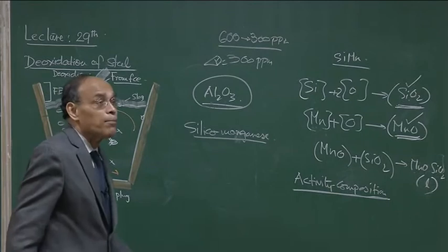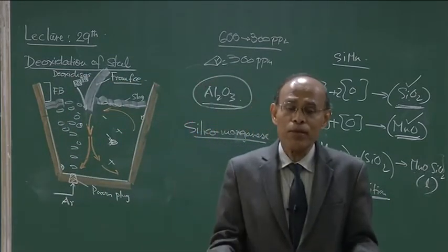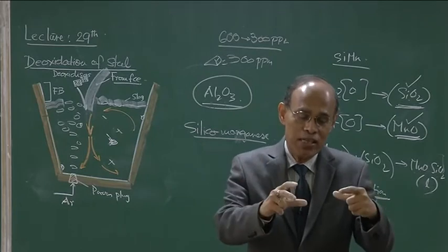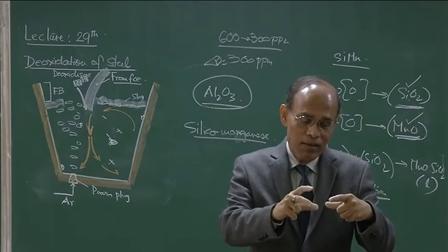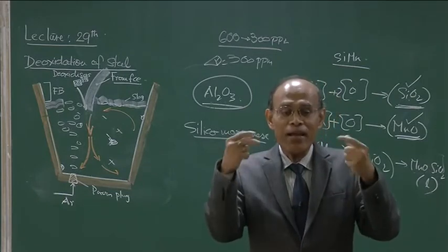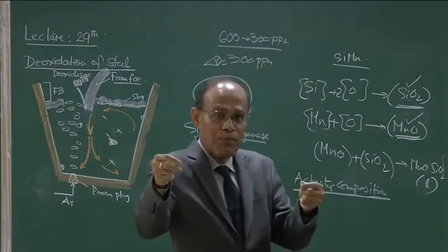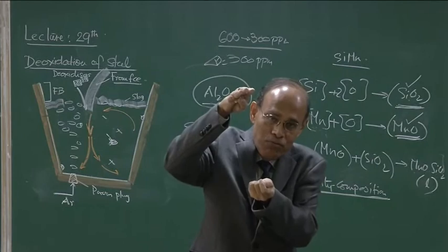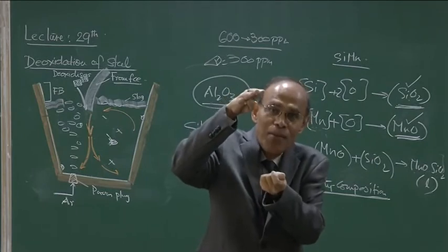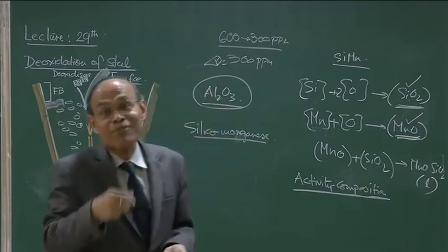You must also understand that, for example, if you want to do a deoxidation with manganese silicate, ferrosilicon, then after some time you may do the final deoxidation from 300 ppm to 100 ppm. So, the first stage reduction is through silicomanganese, and the final stage of stringent reduction is through aluminum addition. Then you add aluminum. In that case, what happens? More complex phases can form.